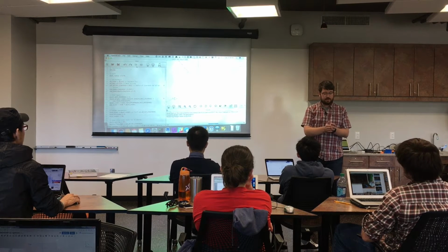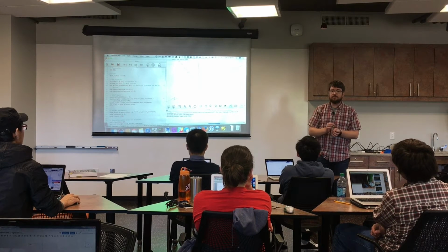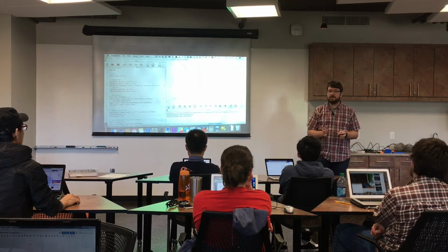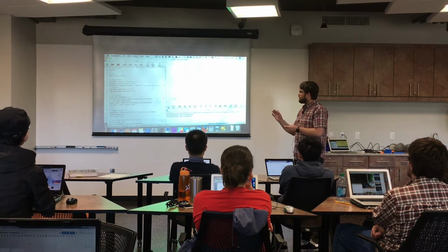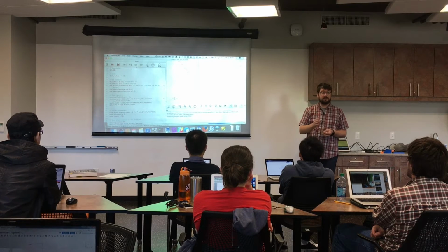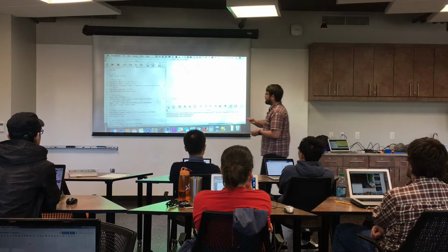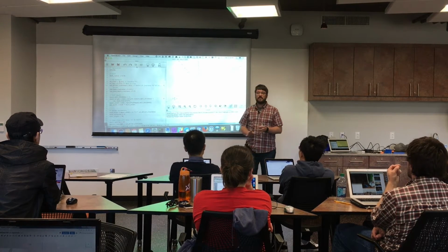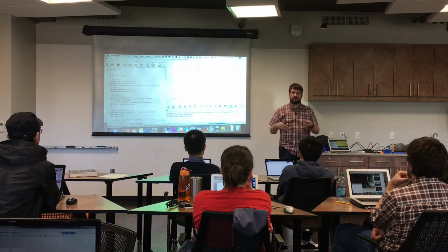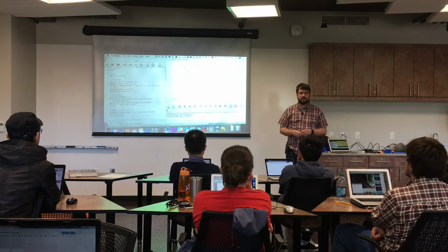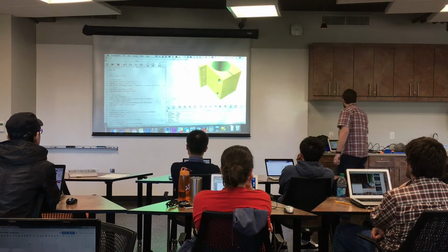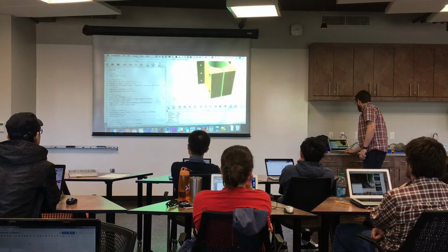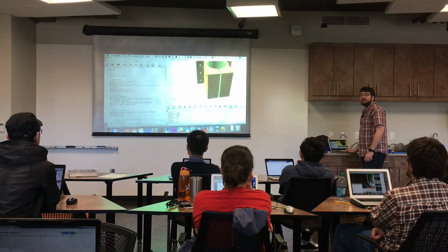Like say you had a part that held tubes in a centrifuge. Well, maybe 3D printing might not be the best way to make that if it's going to be really high speed. But you could have a parameter that says number of tubes, and you could enter how many tubes you wanted, and it would completely redesign the part to hold that many tubes for you based on the functions and the rules that you've put in there. So that's one really nice thing about these parametric tools. Yeah, so now you can see that those holes all changed size because I changed that variable.